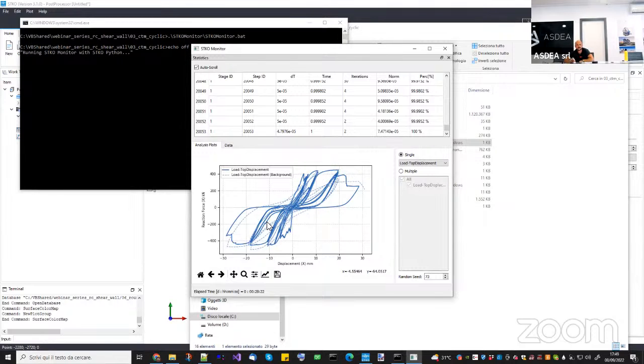But the point is that, being able to recover the plastic deformation and load back to this point here, you start accumulating extra damage. While in tensorial models, you will start accumulating this extra damage much earlier because of the shift of the plastic deformation. So the cyclic behavior is something which can be quite important if you think your model will be subject to this kind of loads.